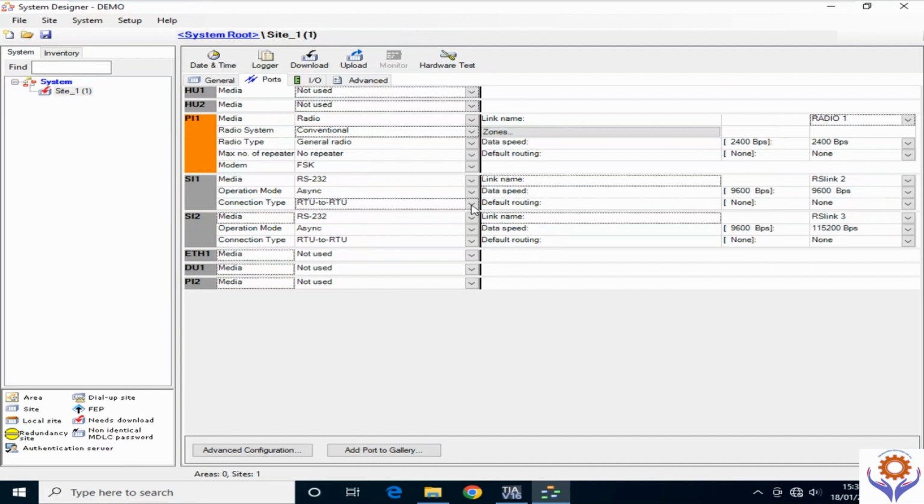Okay, for example, now I am going to configure for third party protocol, so I will use RS485, and I am going to select here multi-drop or third party protocol, or what you are going to connect, third party protocol, and connected to master or slave. So it will be connected to master now. If I put this one connected to slave, you will connect to the power meters or VFDs or any of third party slaves.